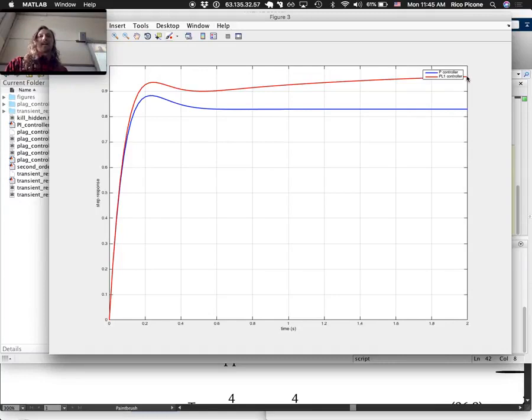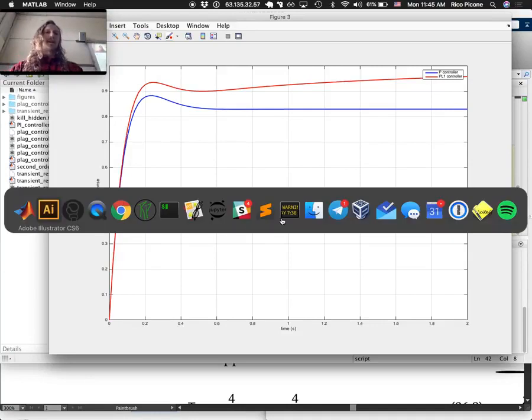The steady state error here is still maybe going to be like 3%. It needs to be 1.8%, so we're not quite there. We could simulate out further, but we want the steady state error to go away faster. So we're going to move these leftward for our second design.